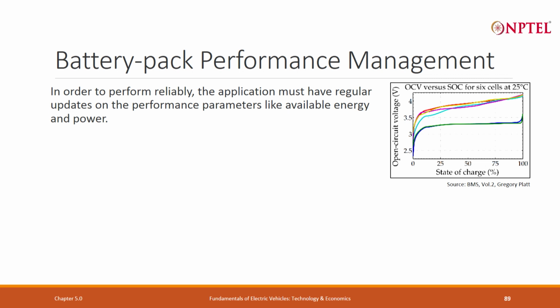The second part is BMS through hardware and software, whatever is its limitation, what we have said, should give you that. If I have said my battery pack can give you 40 ampere current, my hardware should be robust enough to give you 40 ampere current, and software should allow it to go up to 40 ampere current.